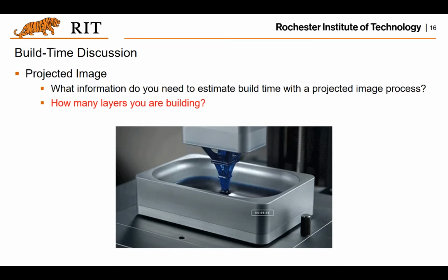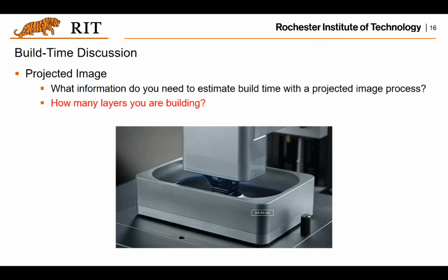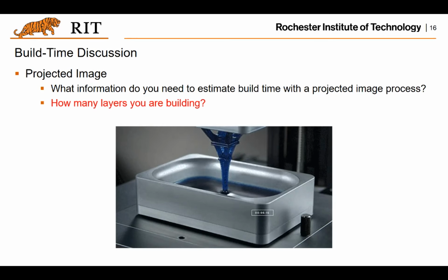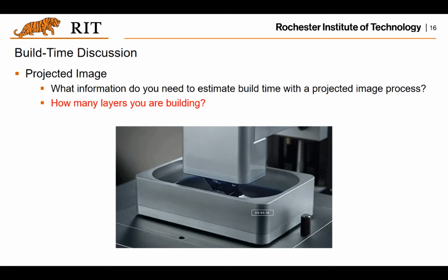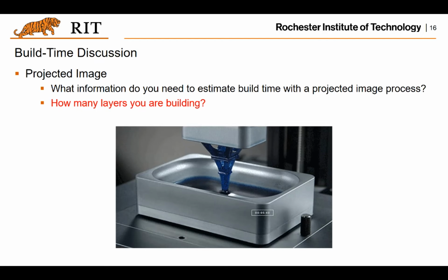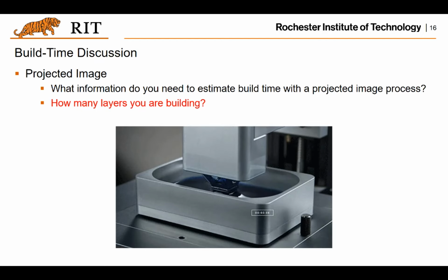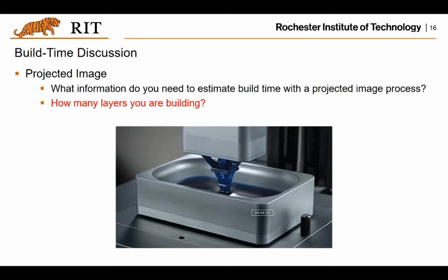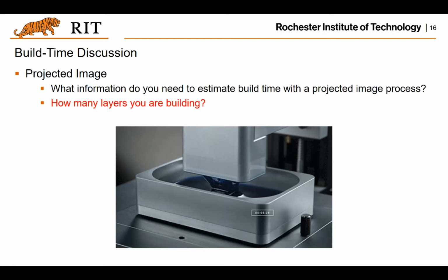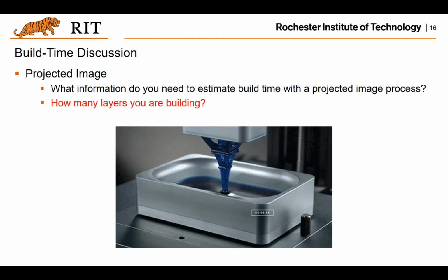Because there's no handling in between the two layers for the CLIP process, the build time will only be related to how many layers there are and how long it takes to cure each layer, right? That's the only time left for this CLIP process. So you don't have time in between the two layers.